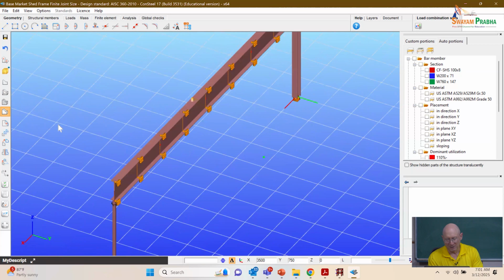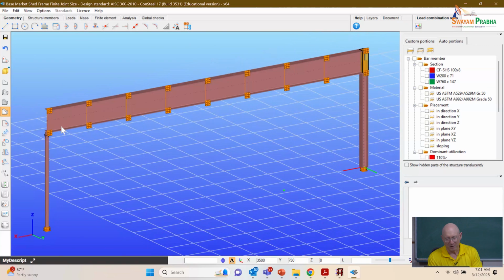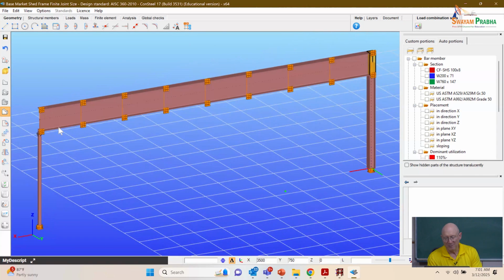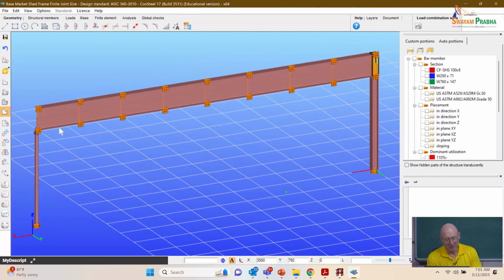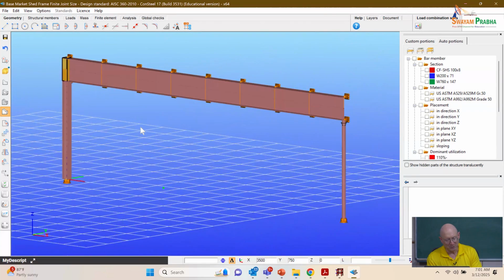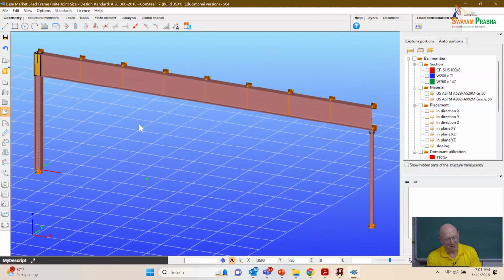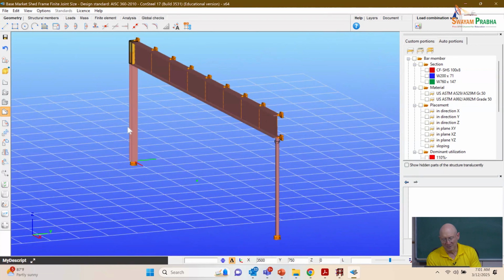We've got the out of plane bracing similar to the L frame. They are top and bottom flanges on the roof girder. We've got simply supported boundary conditions in plane but resisting twist there at the base.